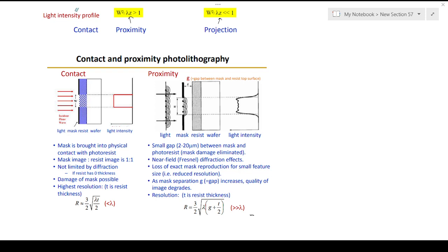And in the optical projection lithography technique, we already said that we will be utilizing the Fraunhofer diffraction situation. The light will be coming from a far distance. In order to convert that light exactly onto the mask, we need a converging lens, and further we need a lens to focus it on a screen.